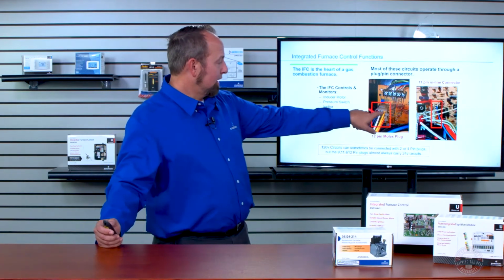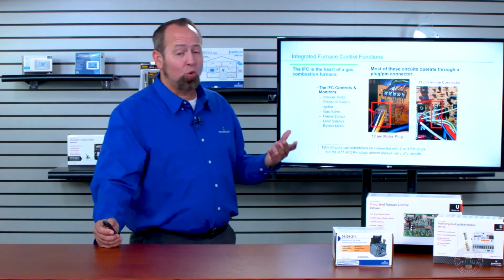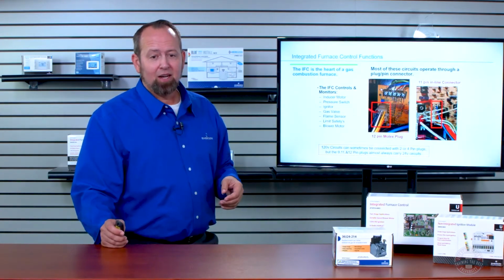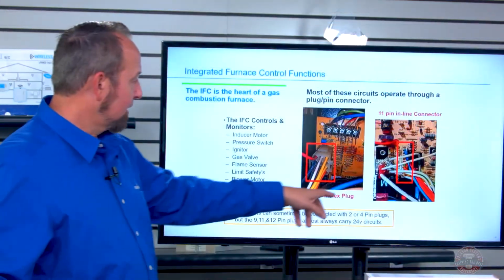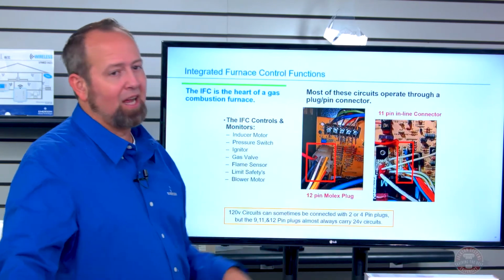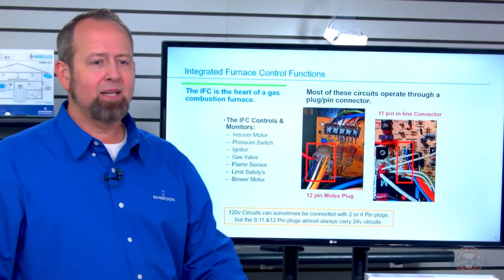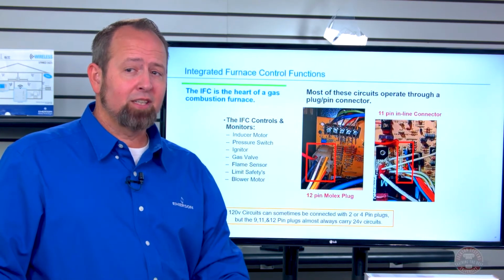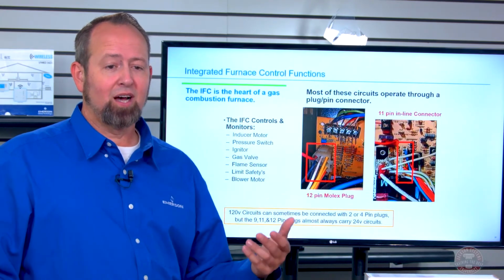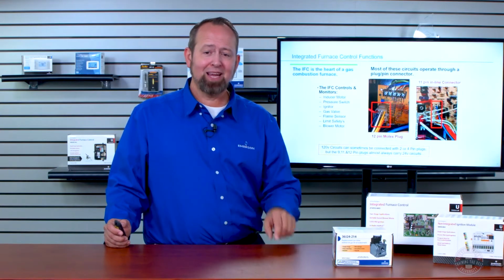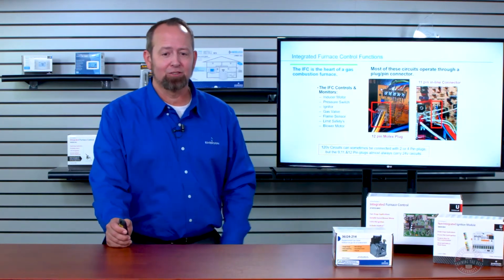And there's two styles. This style right here is a 12-pin connector that we call a Molex plug connector. The other style is an 11-pin inline connector, and the 11-pin inline connector is typically used with the Carrier controls. Carrier infamously decided that was what they wanted to use. And so those are the two main styles of plug connectors.